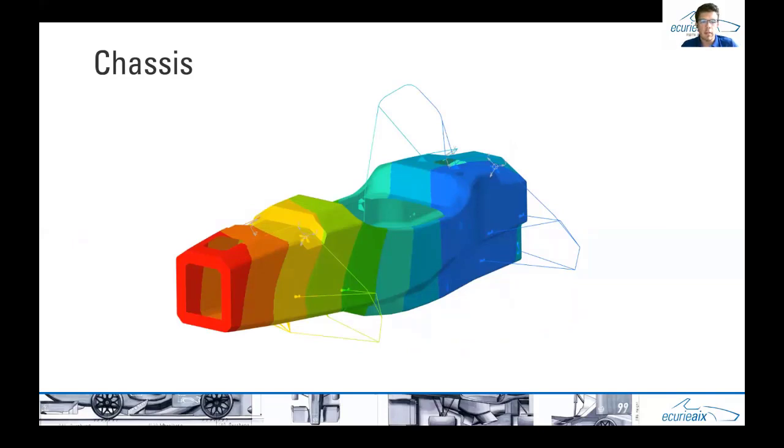You can see that the red part of the monocoque deviates a lot, which means that there the monocoque has the most torsion. So then we can measure the displacement from the point where the force acts and calculate our torsional stiffness.